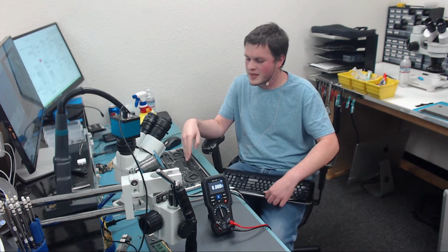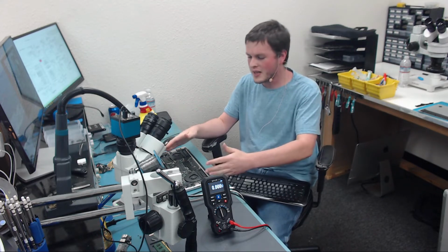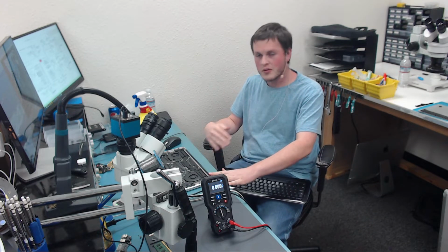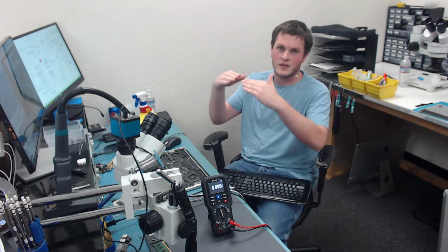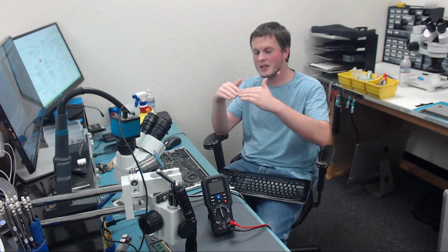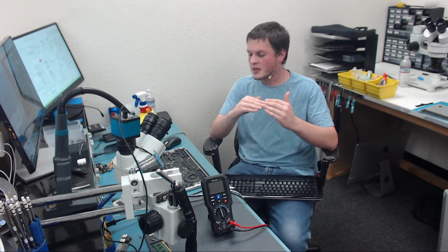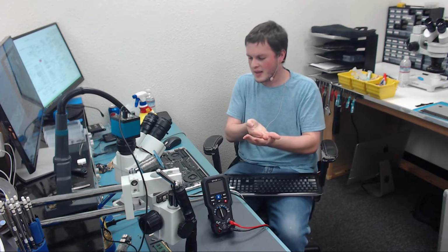So how this happens is this board is very flexible, and it flexes in the enclosure. So over time, the shock of setting it down and just doing regular things is going to cause the board to flex, and that chip is right on an area of the board that flexes. So it's right in the area that it's going to flex and cause the solder joints on that chip to break. So what they did is they put a little piece of rubber on this chip so it mashes the chip against the keyboard.